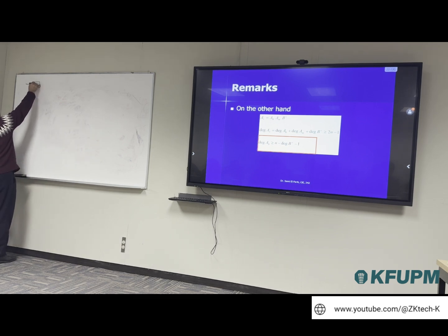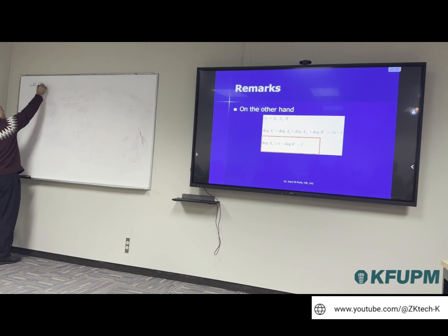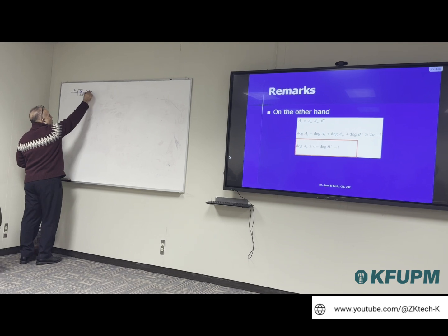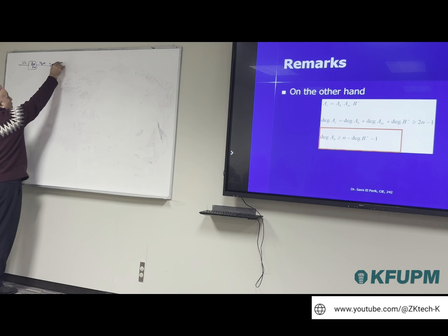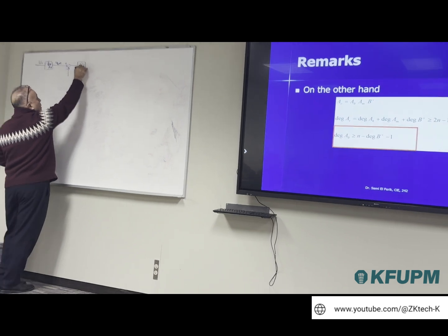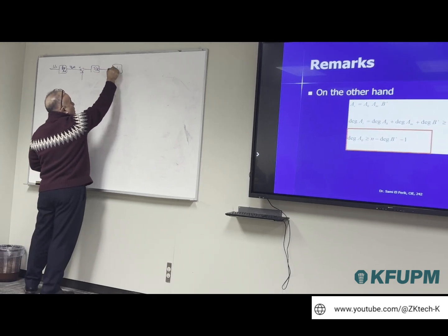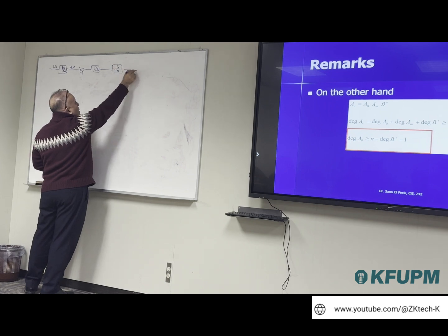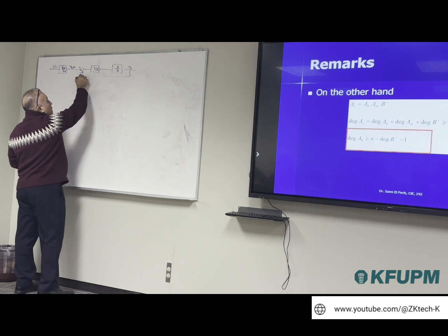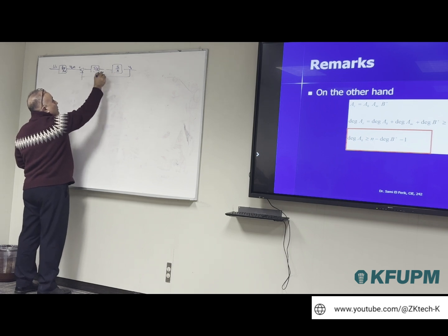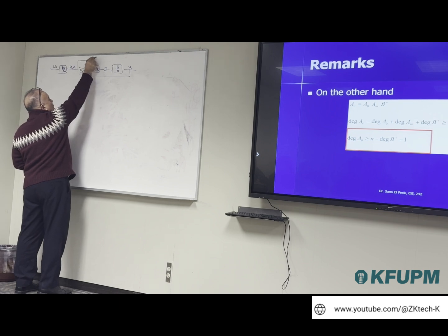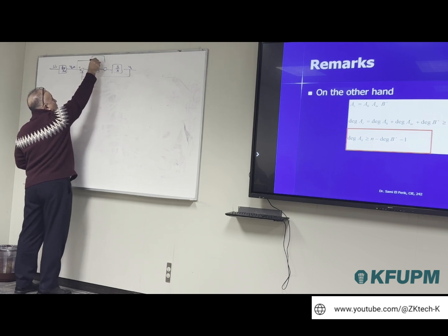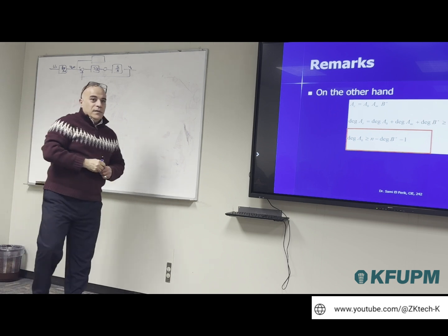So we said this is BM over AM. This is my reference model. This is my reference signal. My YM comes here. Then we have Y that comes from the other side. It goes through S over R. It goes through A over B here, B over A, and then it will generate Y. And then we have at the middle here this term that will be multiplied by the inverse. And the inverse, I'm going to write it in a different color.